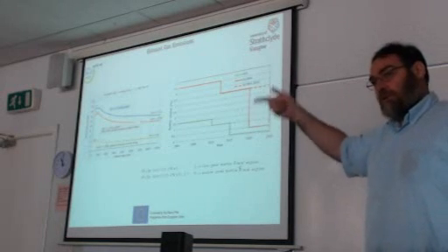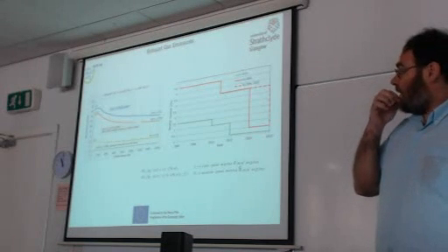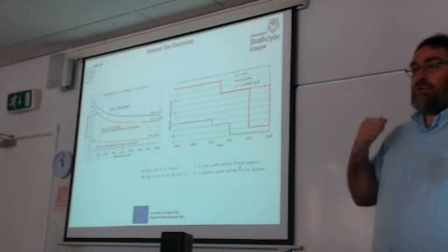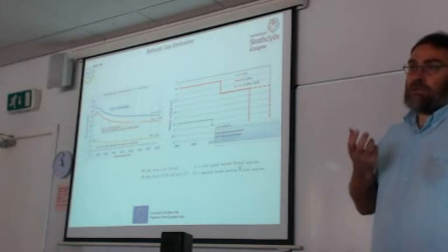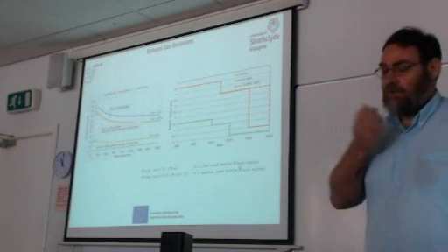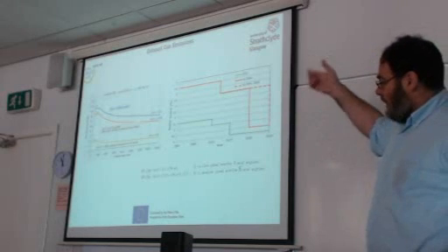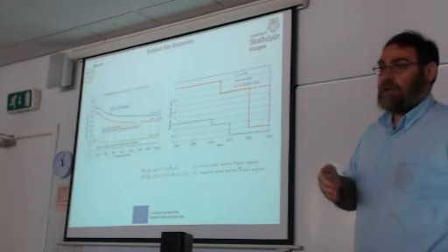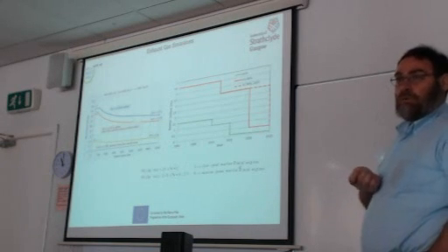The emission level is grams per kilowatt hour. This does not mean that the engine will emit less NOx, because the amount of NOx emitted depends on the engine power. So if you have an engine with, let's say, 10 megawatts power, you need to multiply this factor times the power of the engine. So actually, this is specific NOx emissions in grams per kilowatt hour. Now, the reason comes from the fuels used by the two-stroke engines, heavy fuel oil. Heavy fuel oil is a very low quality fuel, so you expect that the engine should emit higher NOx levels. But, as I said, this is grams per kilowatt hour. It's not the absolute emission.